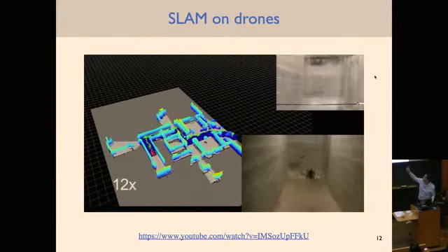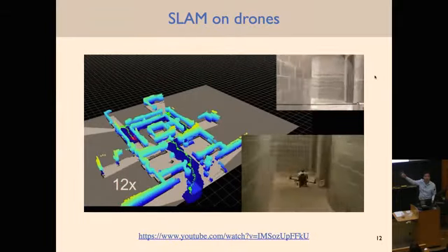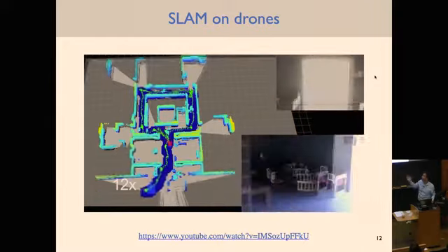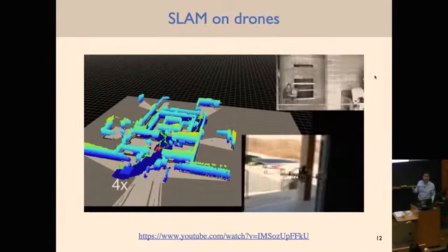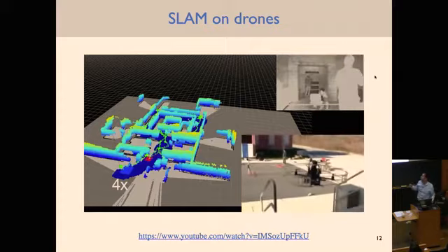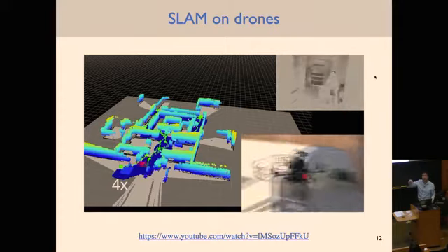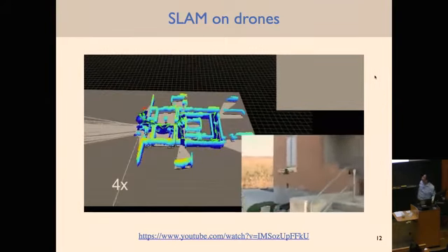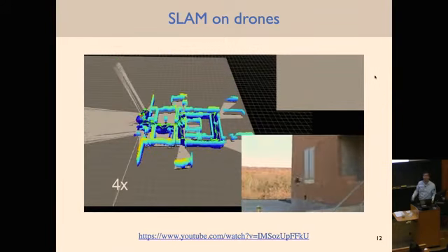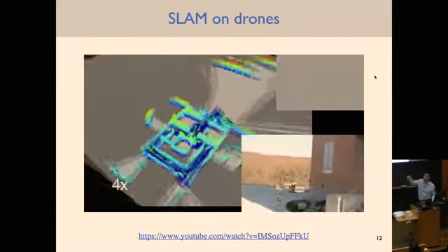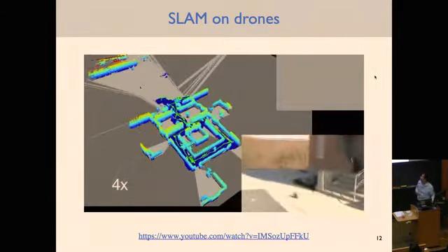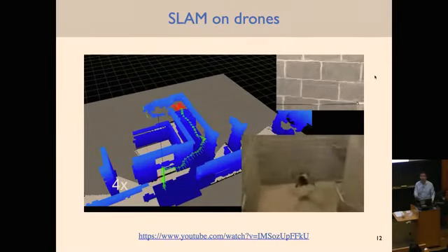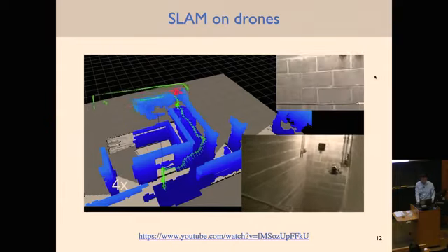One thing to keep in mind is that if you see drone videos indoors, these are GPS denied environments. GPS denied as in you don't have good GPS localization, and so the localization challenge is harder. Outside, for instance, you can get a decent GPS signal, and so you can localize yourself pretty well. But as soon as you get indoors, you can try this with drones that have GPS, the GPS estimate just gets completely wacky, and you should basically mostly throw it away.